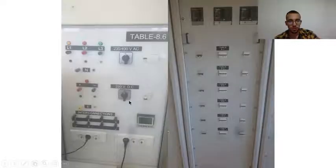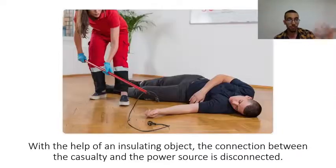These are the switches that we see on our table, and even at the entrance of the laboratory there are some switches, okay? For each table, we can just turn them off so that there's no more electricity. But if we can't turn them off, then with the help of an insulating object, the connection between the casualty and the power source is disconnected. What kind of insulating object can we use? For example, if we cannot turn the switch off and we want the person to get disconnected,